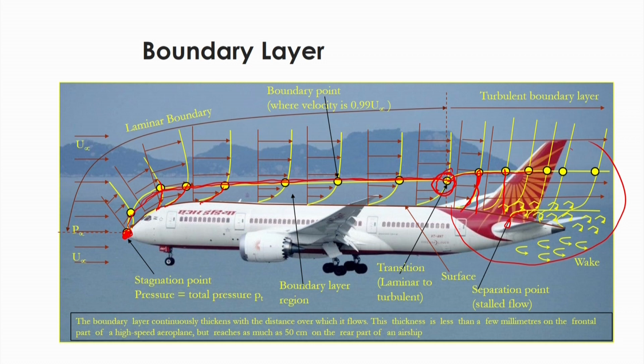So, whenever fluid flows over a solid surface, adjacent to the solid surface the velocity will have some gradient, and this gradient will change along the vertical direction from the solid surface, reaching almost the free stream velocity. The distance up to which this velocity gradient exists, until it becomes 0, is called the boundary layer thickness.